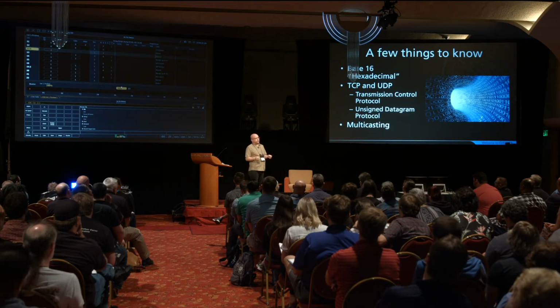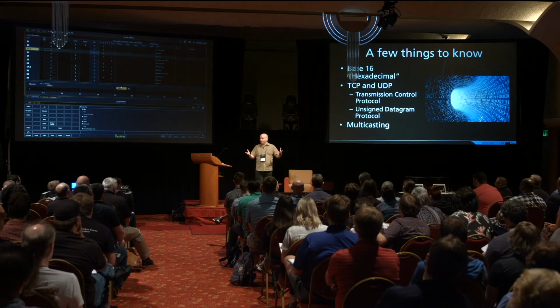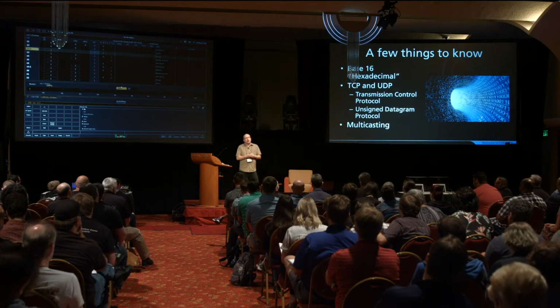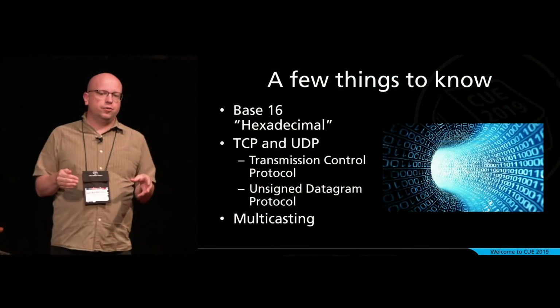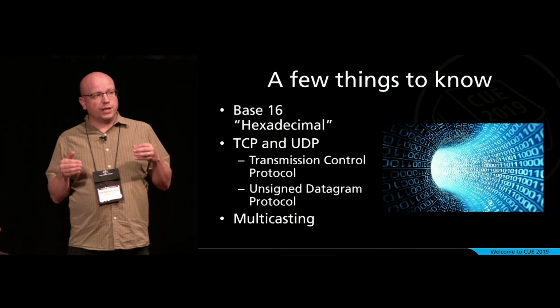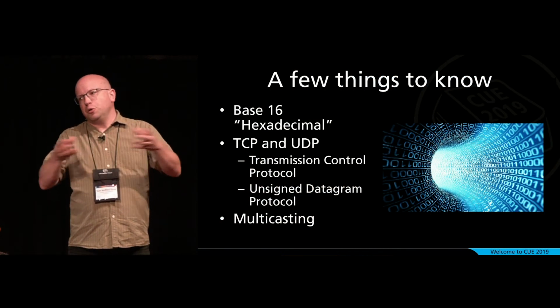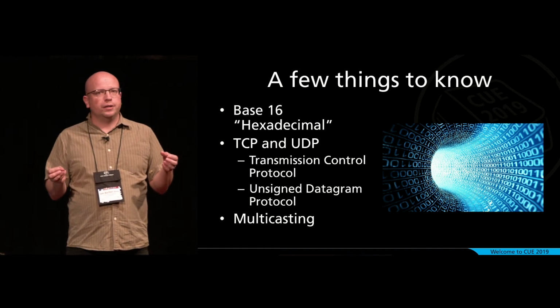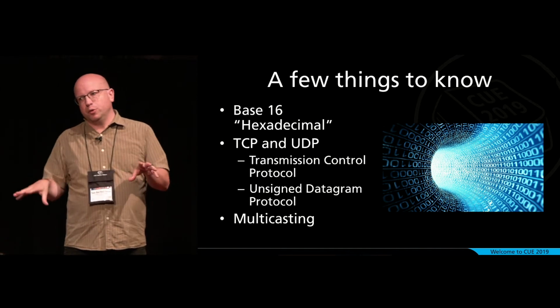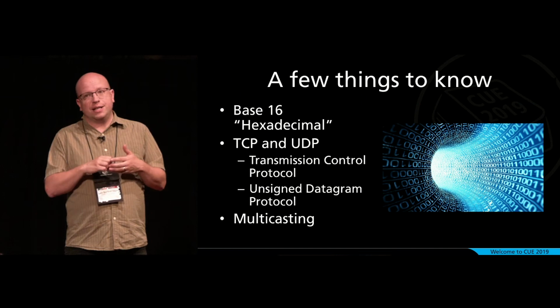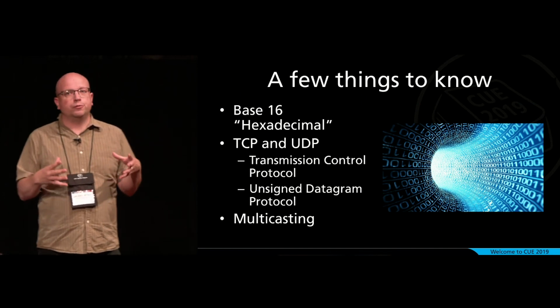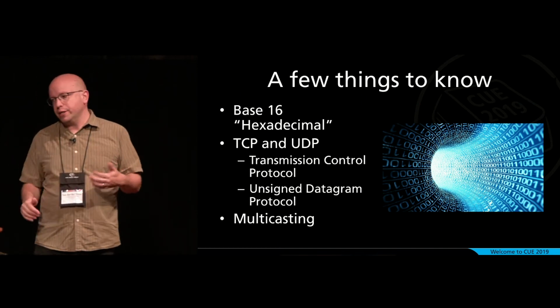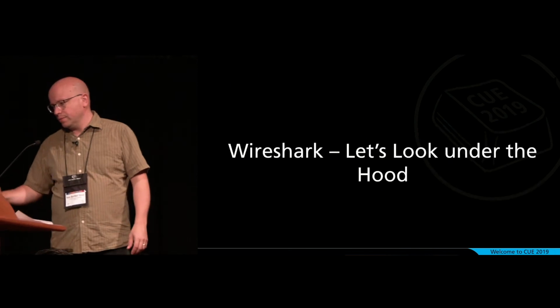And multicasting. We had a bit of a multicast conversation earlier where I talked to the front row. Multicasting is heavily, heavily used in our stuff because, again, I'm trying to address 200 gateways and send them all universe 1. I don't want to do it discretely to all of them, but I also don't want to send data that they don't need. So we use a lot of multicasting to get the right data to the right group of devices.